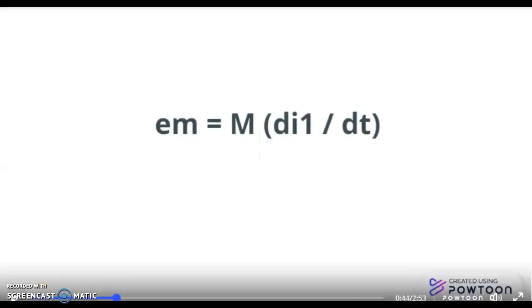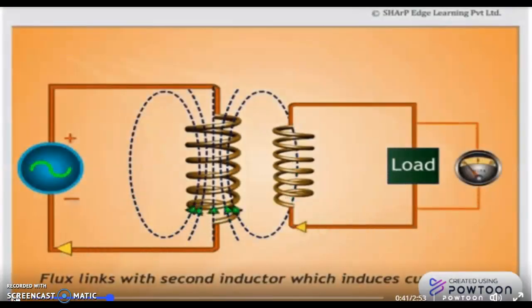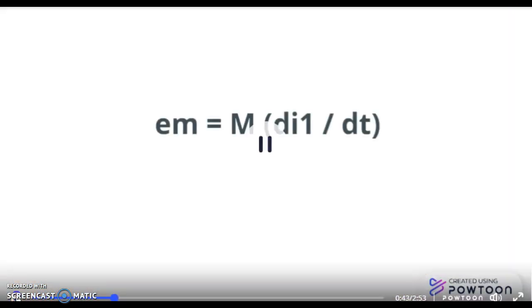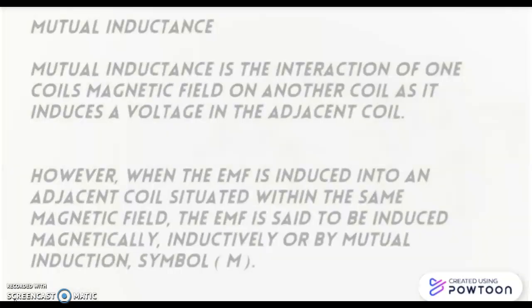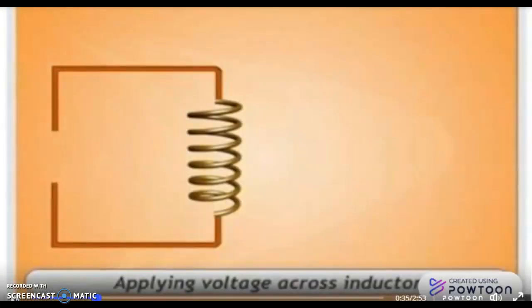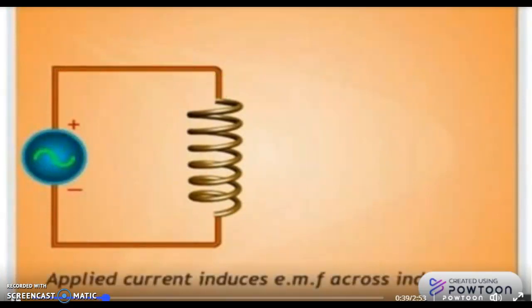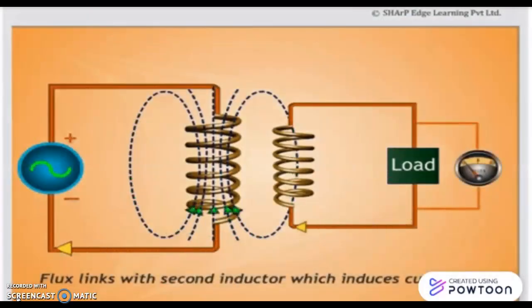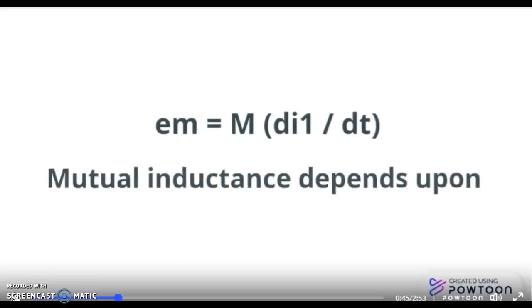And this magnetic force will push and pull on the free electrons, forcing them to move. The key component here is that the magnetic field is changing polarity as well as intensity. This change in intensity and direction of the magnetic field constantly disturbs the free electrons in the secondary coil, and this forces them to move. This movement is known as electromotive force or EMF.